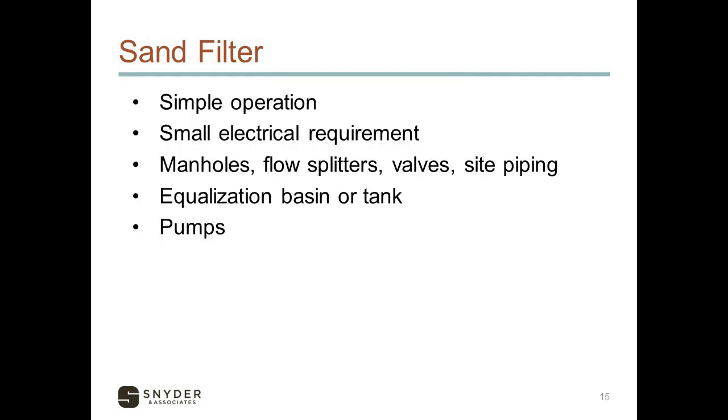These operations are still fairly simple to manage. They have a small electrical requirement. They do have manholes and flow splitters, valves and site piping involved. And often they have an equalization basin or tank on the front side of the sand filter because it's not a 24/7 pumping of water into the sand filter in those cases. It's more they pump 5 minutes each hour or something like that, and then they let the system work.